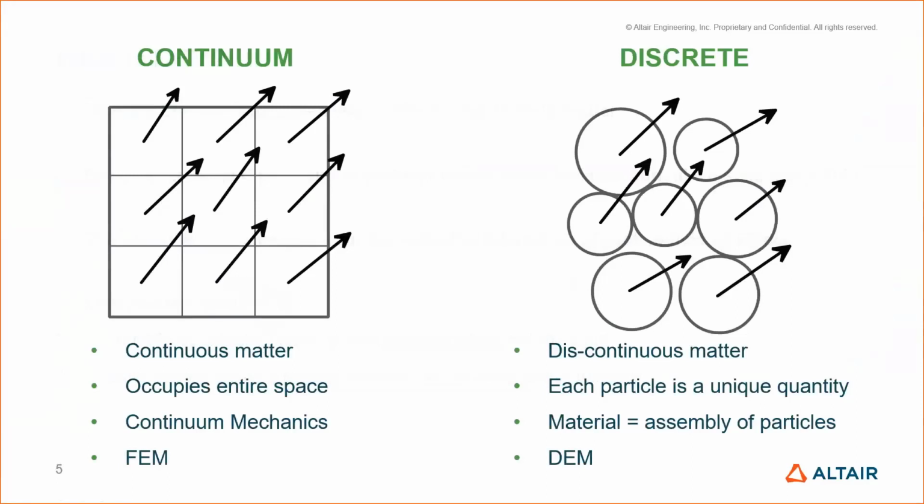When it comes to simulating particulate systems, there are two main modeling approaches which could be used, the continuum and the discrete method. In the continuum approach, shown here on the left, the behavior of the granular material is described by constitutive laws. These laws are commonly expressed in the form of differential equations, and they relate to mechanical field variables like stress and strain. Modeling a substance as a continuum completely fills the space it occupies. As a result, the behavior of the individual particles is ignored, and the resulting equations are solved, and this is a method similar to finite element method.